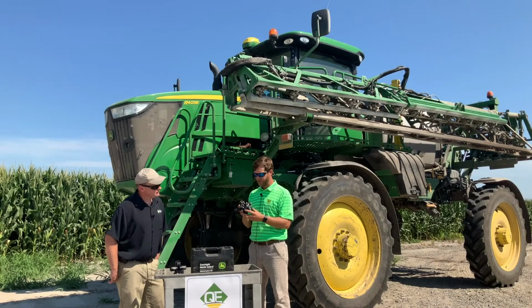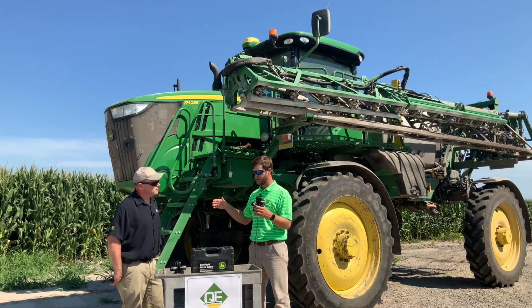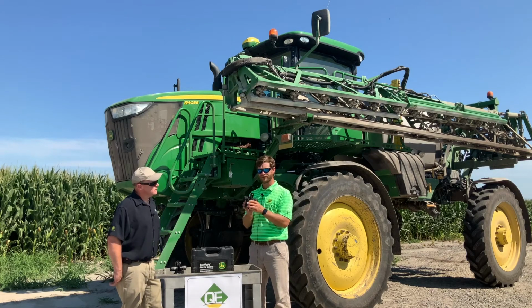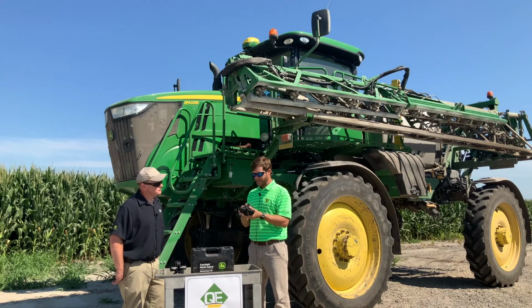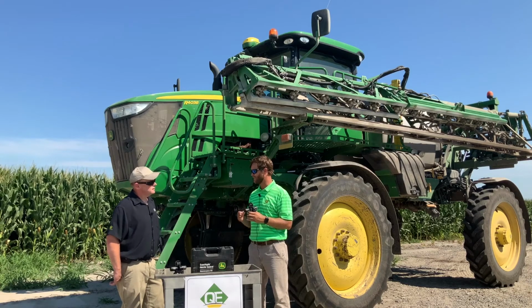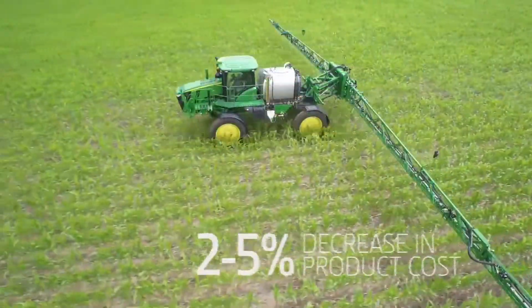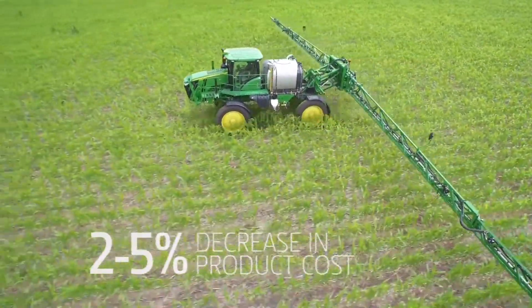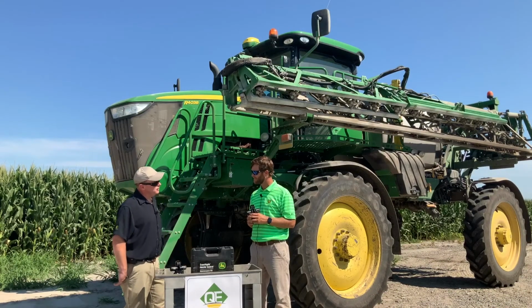Yeah, so Stephen, if we think about conventionally how we've sprayed, we've had booms that may have sections that vary anywhere from 8 to 11 foot. With the individual nozzle control, we're turning the nozzle on and off independently. That allows us to have precise applications where the product is needed on the crop. So being able to do that also gives us the ability to have a reduction on our input cost anywhere from 2 to 5%. So Jared, tell us how our turn compensation would allow a grower to reduce his input.